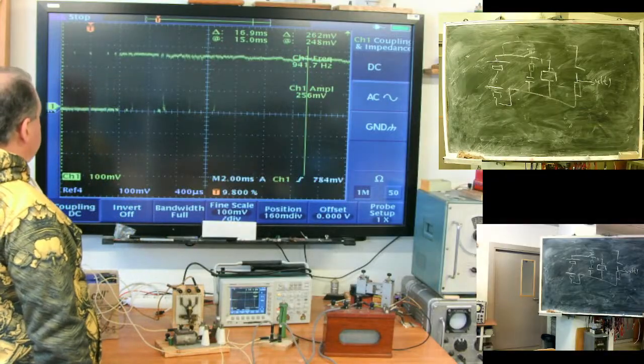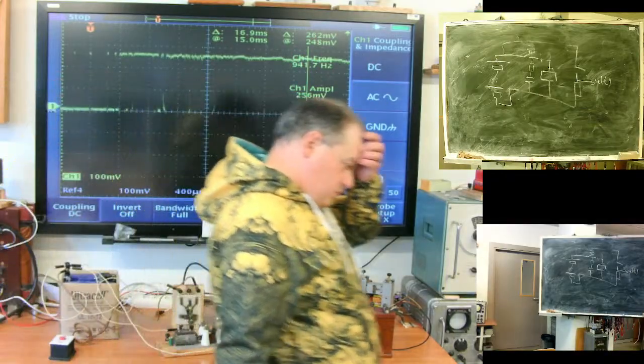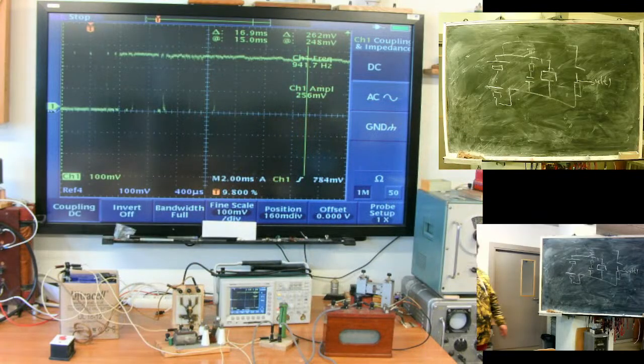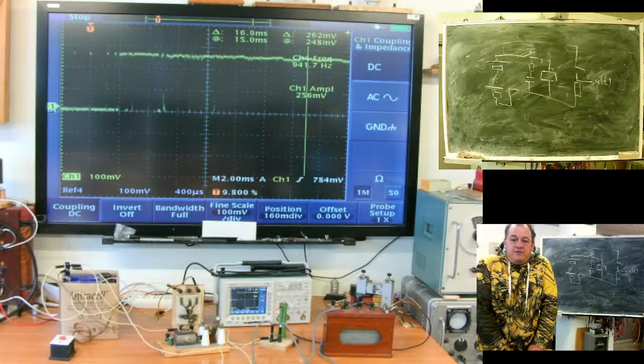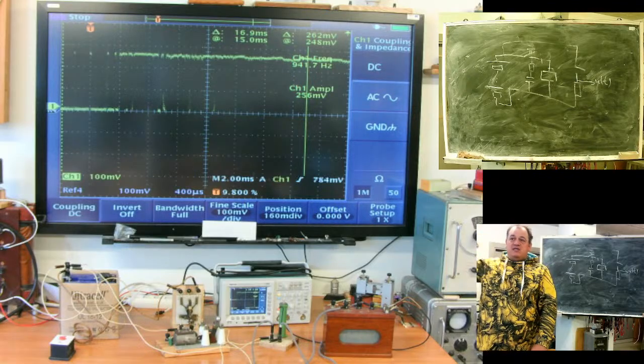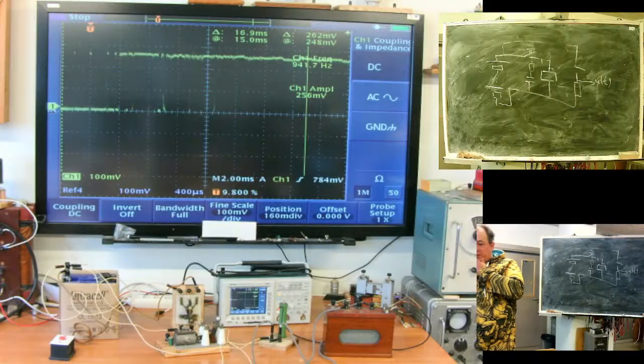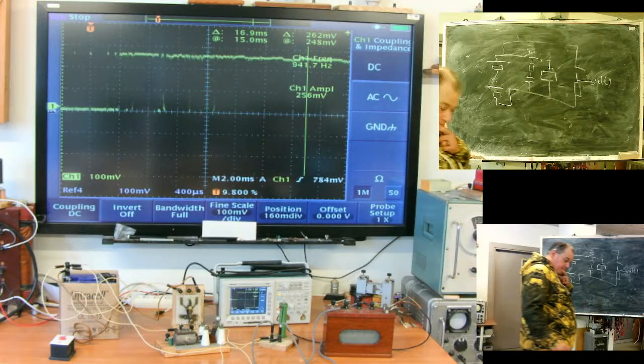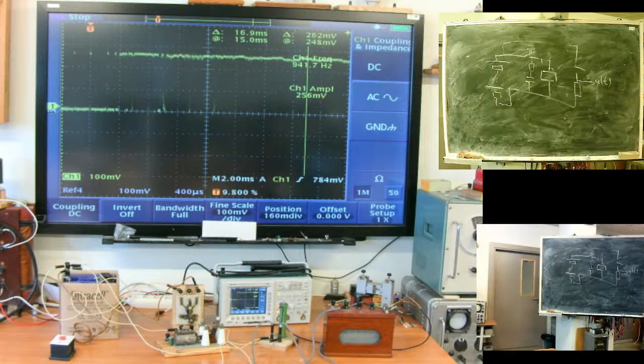Here is the problem. When your input is a binary signal, in real life you will never get a clean 1 instantly. You will get 1 0 1 0 1 0 1. What does this mean? Your input circuit should have what?